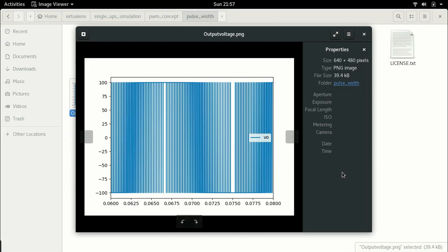So you see the difference? There's a huge difference. This waveform seems like a high frequency switched waveform, and it is a high frequency switched waveform. But actually within this waveform there is a hidden pattern. I'm not sure if it's very obvious, but you see here there is actually a sine wave embedded within this. There is a sine wave. So if you see here, if you track, it goes this way.